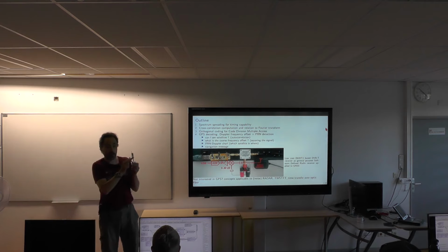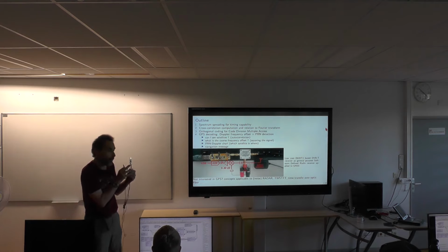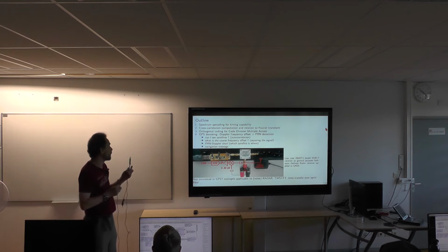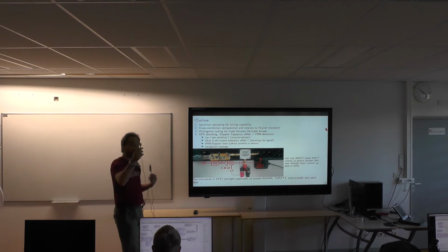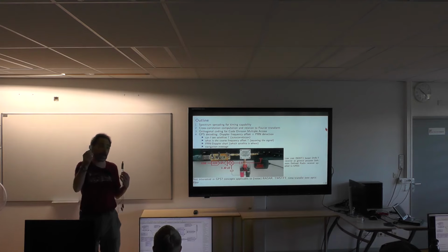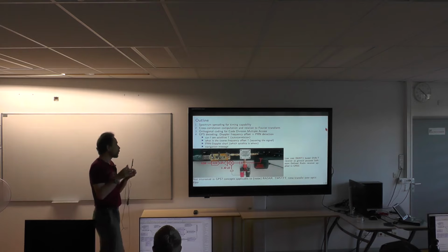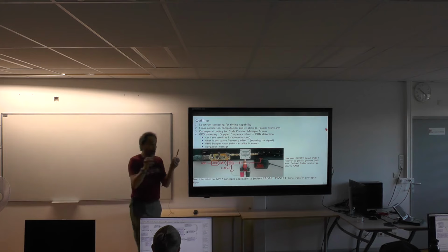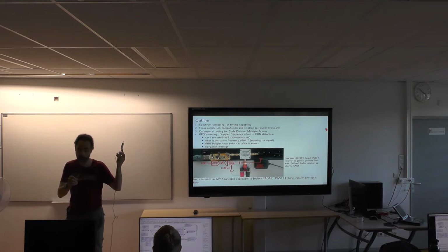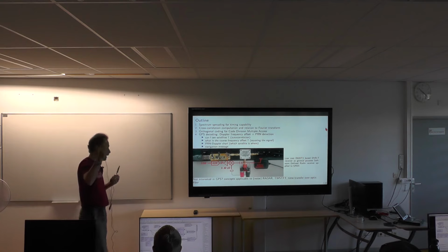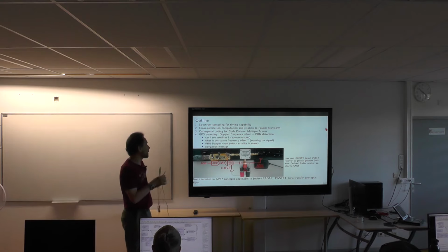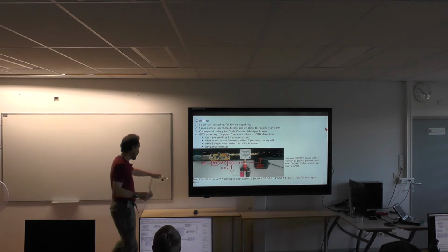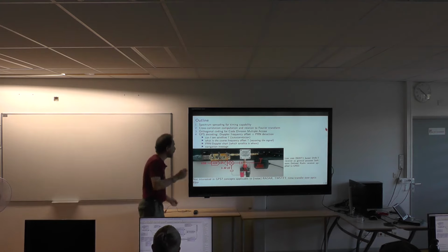We're going to use data collected from a software-defined radio receiver. You might have heard about this RTL SDR. You can find this for about €10 on the internet. You need a GPS compatible antenna. These are active antennas. They have an amplifier. So you will need a bias T to power the antenna, but that's about all the hardware you need. So about €10 worth of software-defined radio, €20 worth of antenna, and the bias T, and you're ready to collect data. So if you want to reproduce this at home, it's an easy experiment to reproduce.